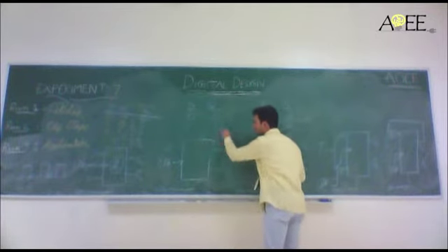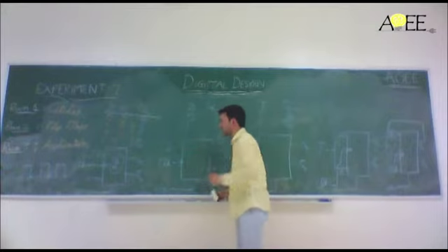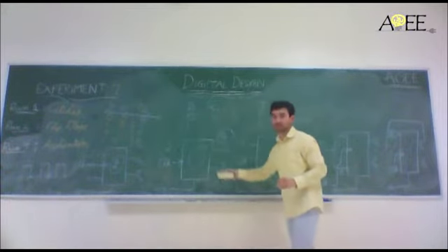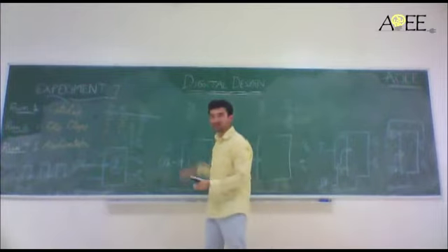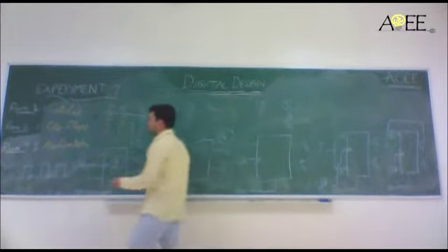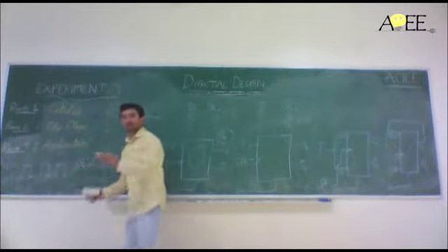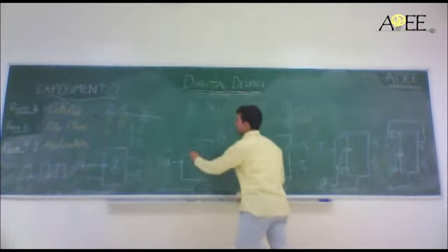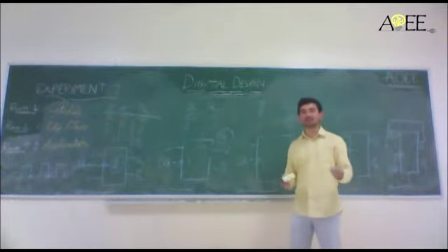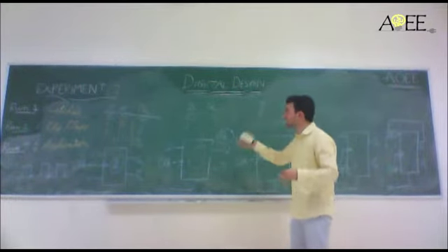What is the state of, or whatever is present inside the flip-flop, you give, you get the same thing. Now, the advantage of having something like that is that it will delay, because output will be coming after some period of time, after the next clock pulse. So that's why this will help. This will give the delay, whatever is required in any circuit. It is required at times.